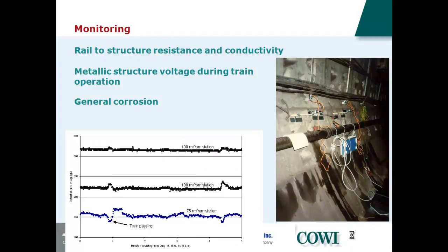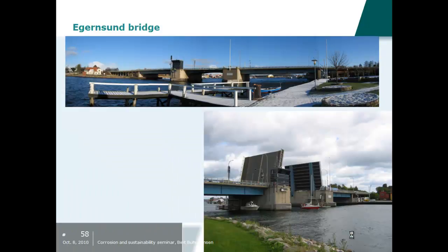Also, we did measurements where we had a reference electrode we mounted on the tunnel elements, at 3 different locations during operation of the tunnel, and we could then follow the peaks from trains driving past this location. This is another example. That was as much as I had just now on metros and stray currents. Just on that one, I have another example in a minute.